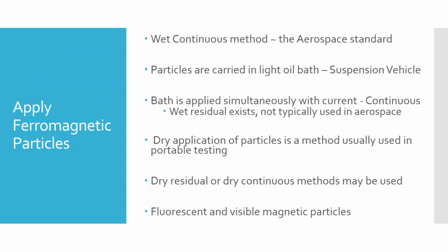So our particles are carried in a light oil bath. And the light oil bath is called a carrier solution. It's very similar to mineral spirits. It's a very thin, oily kind of liquid. And what it does, it's called a suspension vehicle. So the particles don't dissolve in it. They're always suspended. And so we have to mix them up or agitate them.